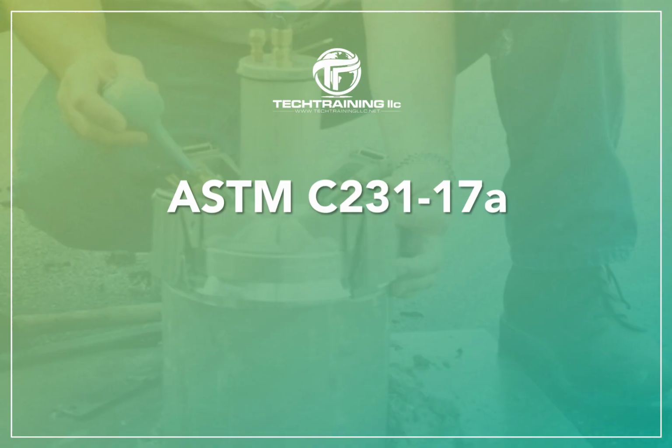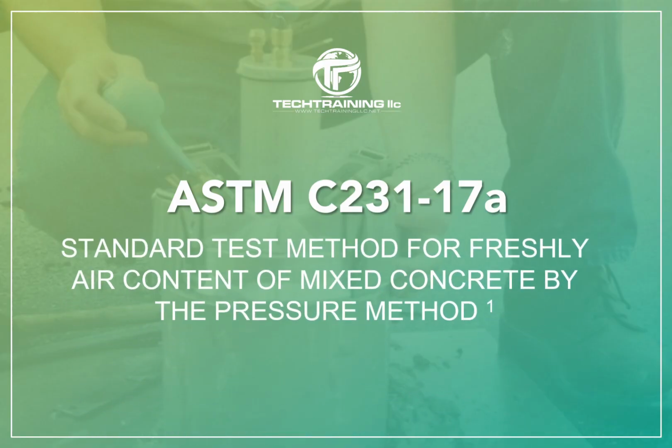ASTM C231 is the standard test method for air content of freshly mixed concrete by the pressure method. This test method covers the determination of the air content of freshly mixed concrete from observation of the change in volume of concrete with a change in pressure.